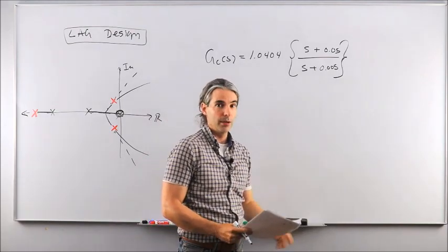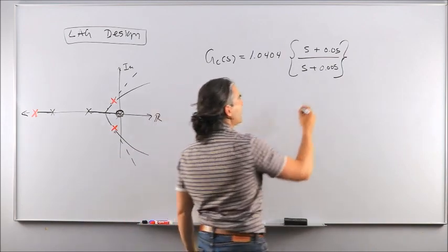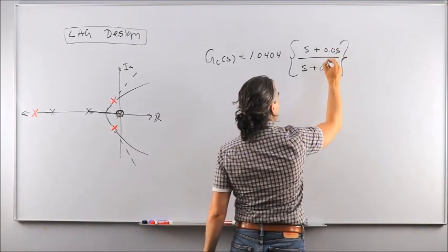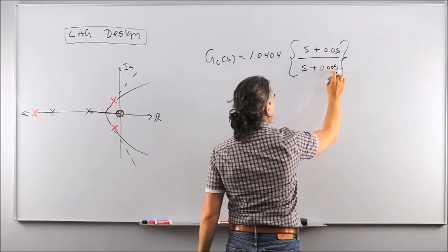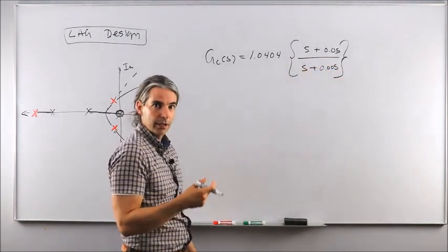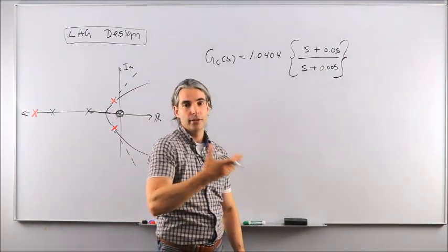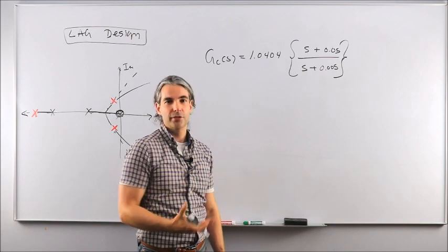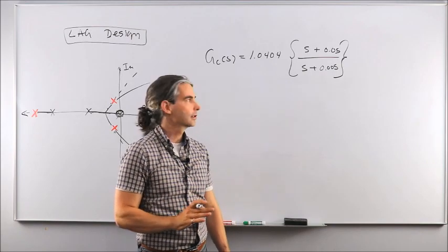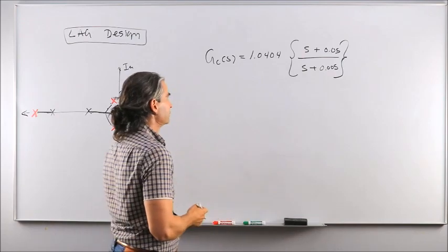You don't need to do all of that because you had selected, as a good engineer, positions for the zero and the pole of the lag compensator intuitively, yet to maintain the beta factor that was extracted from the desired specifications on the steady state performance. Okay, that was our beta equal to 10 in this specific scenario.